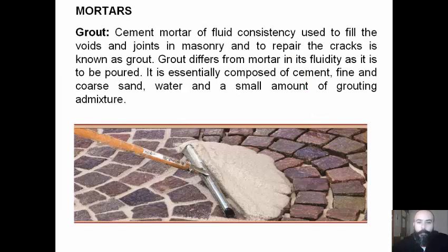Grout, a cement mortar of fluid consistency used to fill the voids and joints in masonry and to repair cracks, is known as grout. Grout differs from mortar in its fluidity, and it is to be poured. It is essentially composed of cement, fine and coarse sand, water, and a small amount of grouting admixture.